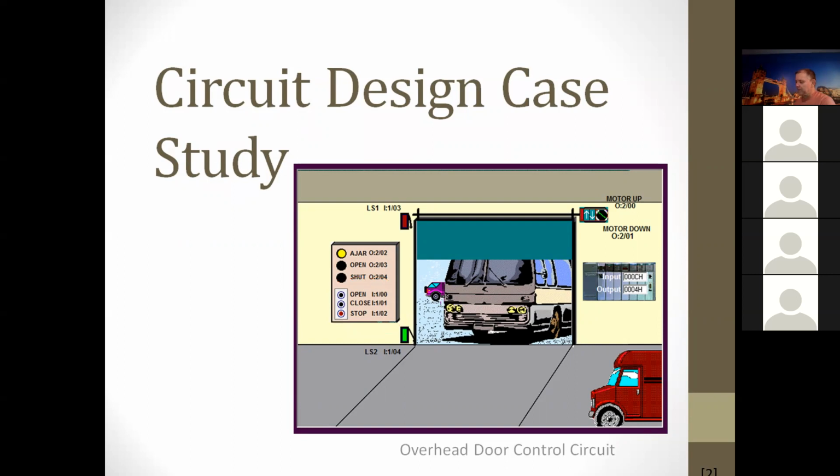This is one of those roll styles. So you can imagine this is a big cylindrical roll that rolls up the garage door. Do you understand? It's not like a flat one that opens up. It's like a rolling one. And as it rolls upwards into its little roll, this limit switch is held closed. It's a normally open limit switch held closed by the door. And when the door reaches the top, it will spring open. Are you good with that?